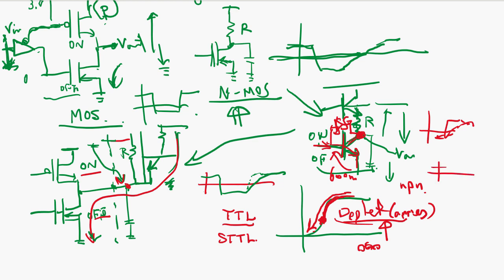So usually it's a very slow rise time like that. It becomes like this. So this is much improvement on the speed. Okay, in switching, how do you measure the speed? You measure the speed at the digital threshold to threshold time.